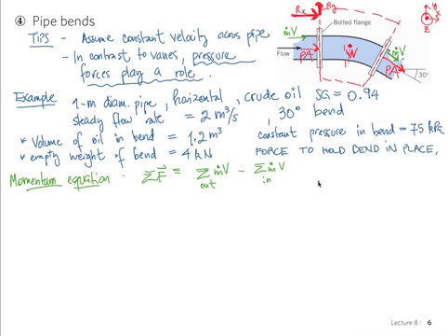Yes? Why don't we put reactions on the other? We do, but we've just taken them all together and bunched them into just one reaction. And we don't worry about those details now. We just have the total final net force on the control volume. Once we find that, then if we want to design the devices mechanically, we can take into consideration how that force is going to be distributed. So we're looking at the net force now.